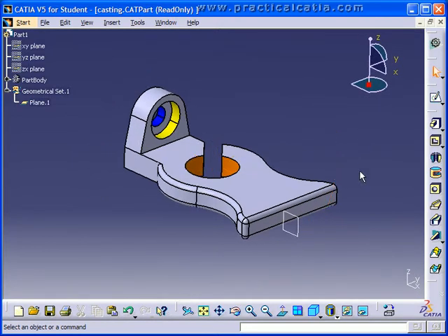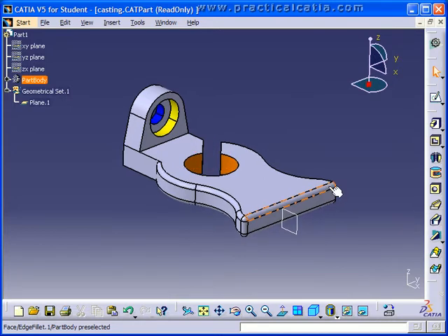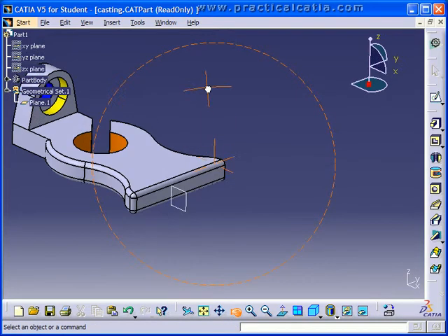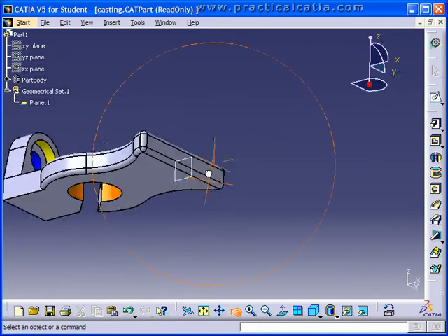Now, there comes a time when you want to change the rotation center. In fact, that's going to happen quite often. To change the rotation center of the sphere, simply put your cursor over a portion of the part that you want to rotate about, depress your middle mouse button without moving the mouse, and then release. And where your cursor was on the part will then snap to the center of the screen, and then you select the rotate button, and now you're rotating about that.